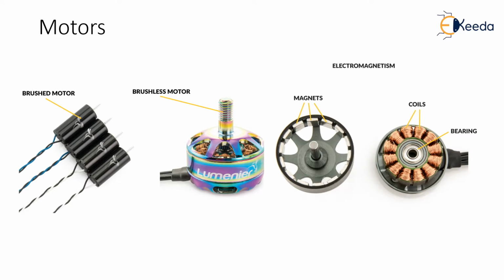The stator is the stationary part of the motor windings and the rotor is the rotary part of the motor, the bell with magnets. Also, there are a lot of other minor things such as bearings, coils, magnets, shafts, etc. Brushless motors come in all shapes and sizes. The general rule of thumb is to aim for a 2:1 thrust to weight ratio. More details about the motors, such as selection of motors, will be covered at a later part in the course.